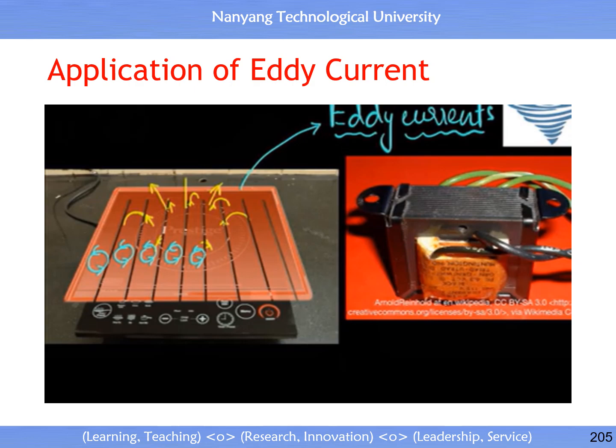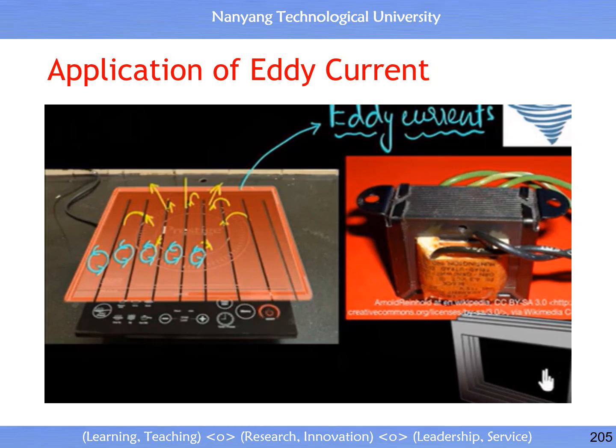Well, the whole idea over here is instead of having one giant block of metal where eddy currents can keep dancing wherever they want, we instead have thin slices of these metals laminated and then glued together. In doing so, we are introducing air, just like over here, and as a result increasing the resistance, thereby reducing the eddy currents. And because these things are all laminated, there is no electrical contact over here, which means you can't have a lot of eddy currents over here. So in doing so, we dramatically decrease eddy currents, and as a result, we dramatically decrease heating losses.